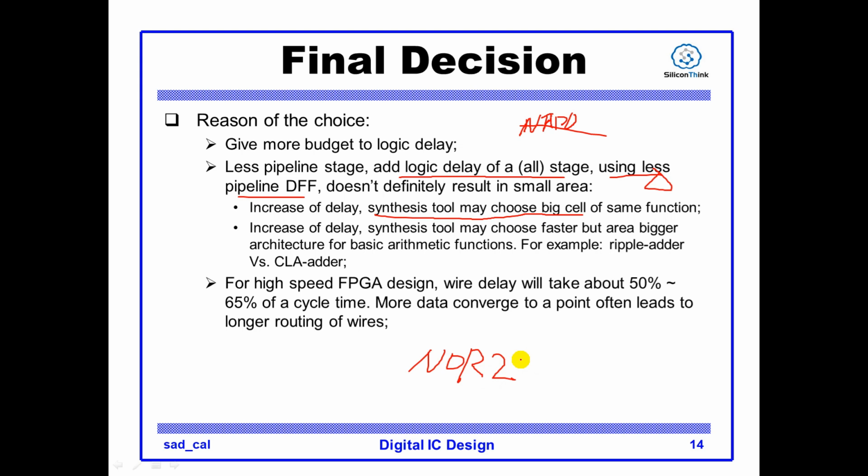I have explained in our first chapter, there is a cell with driving strength of 1 and a cell with driving strength of 2, and even a two-input NAND function with driving strength of 8 or maybe 16, or 4. So these cells have small delay but big area. The function is the same but the delay is different and the area is different.